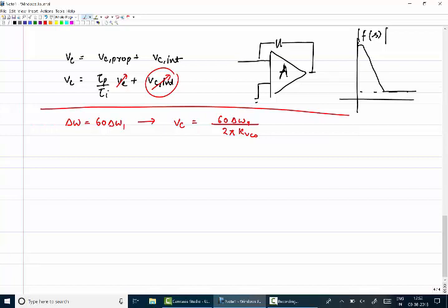If this is my VC, I should calculate what my V error should be. Okay, I can calculate back because my transfer function is also in DC. I can calculate what the DC value of the phase error should be. So I gave that particular V error value. Means I am first calculating, and then with respect to the V error, I can also give my phase error. So I know if it locks, it should lock to these values in a steady state. Okay, what do I do? Then I start my PLL.